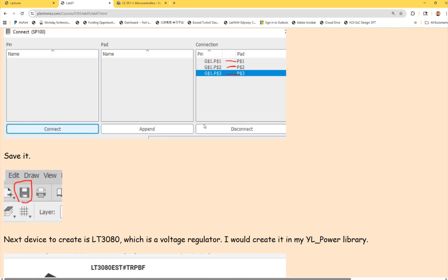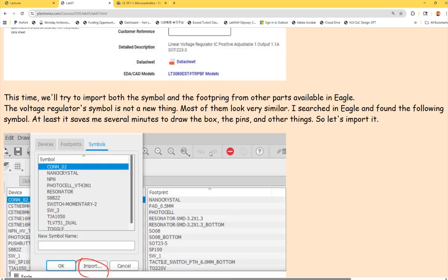I mean, this is just one example. Also for the op-amps, right? Op-amps are generally just triangles, but you can look at the market, from DigiKey. They have all different footprints. Even the ones on our board, we probably have 2 different packages for our op-amps. It's the same concept, right? So the symbols are usually reusable, but the footprints less so, but still.